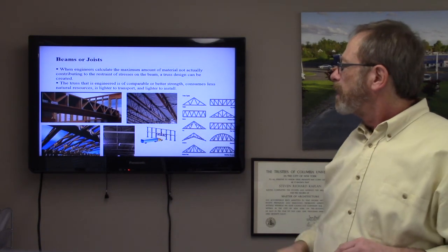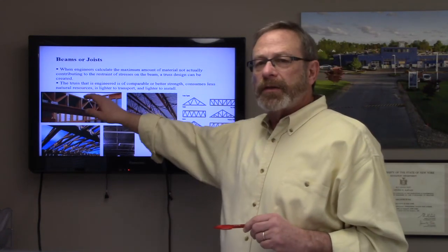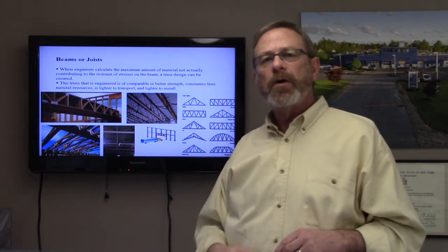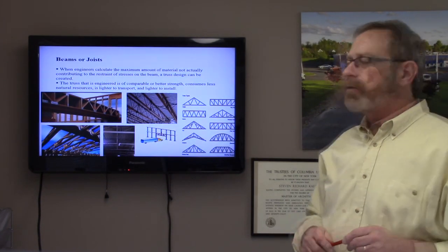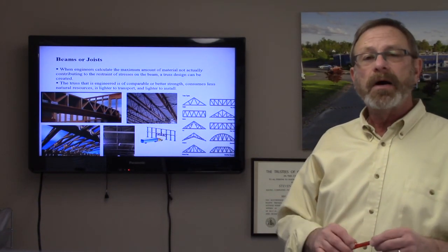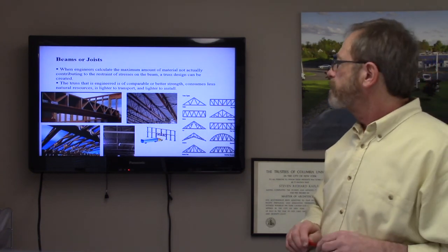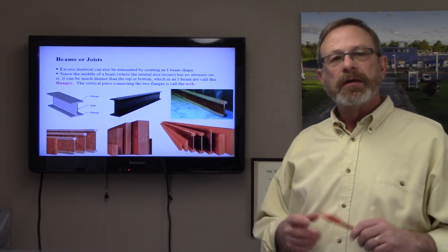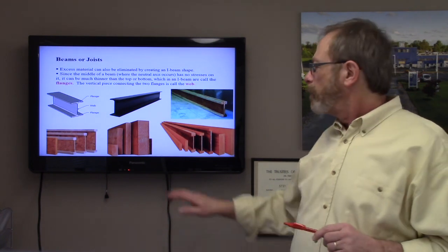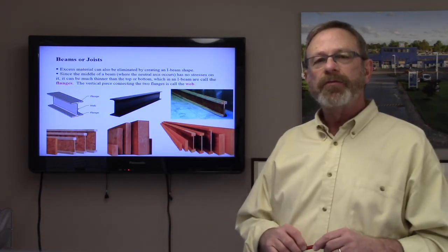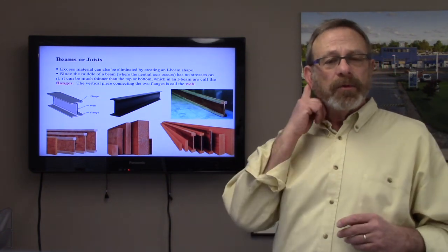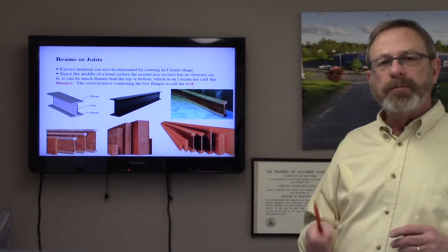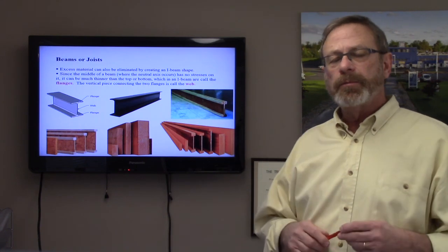So a truss works only at the top and the bottom, and the center is only holding those two edges together. Inside we can run whatever, as I said, pipes, wiring, air conditioning ducts. Whereas typically when we were framing homes, we used standard lumber harvested from the trees that were cut to a manageable size. Maybe a couple of people could carry a heavy wood timber, lift it into place.